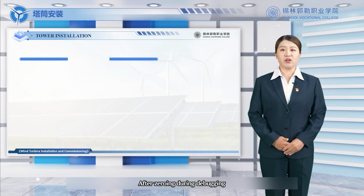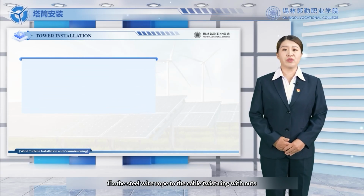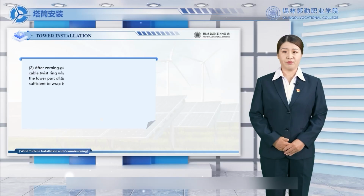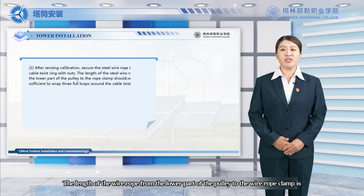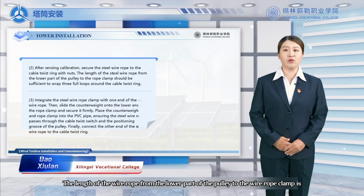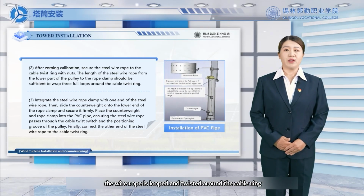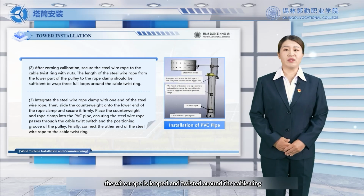After zeroing during debugging, fix the steel wire rope to the cable twist ring with nuts. The length of the wire rope from the lower part of the pulley to the wire rope clamp is the length of 3 turns at the point where the wire rope is looped and twisted around the cable ring.